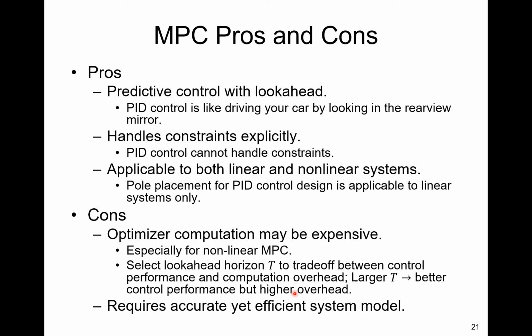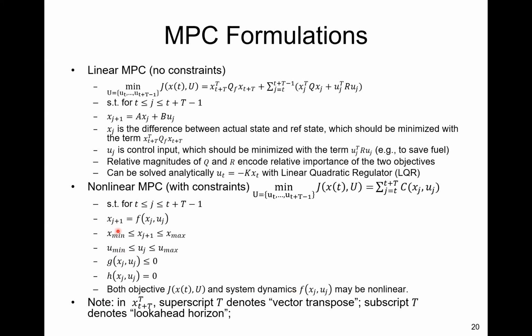You're only making a control decision based on your current state, which is determined by your past. In this sense, MPC is a more advanced control algorithm. It also handles constraints explicitly, whereas PID control cannot handle constraints. By constraints, I mean here that x and u can have lower and upper bounds and may have general g and h constraints.